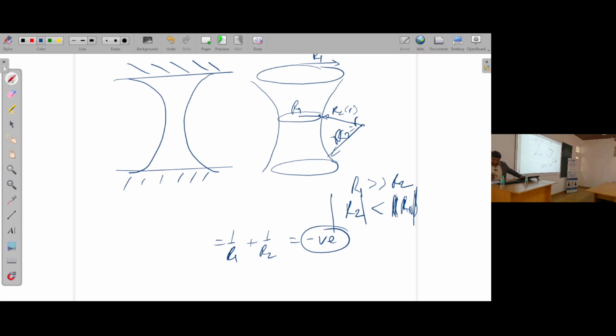If you look at this and put that back in the Young-Laplace equation, you will find that P liquid is less than P gas. That is, the pressure in the liquid is less than the pressure in the gas, and that is the reason why you have adhesion between the two plates. So you will have adhesion. This is a critical adhesion criterion.